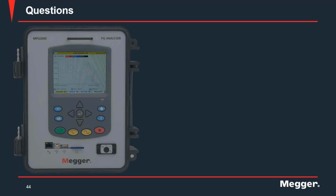One of the key things you may also end up getting into is what's called supra harmonics. These are harmonics that go up to about 150 kilohertz. And really right now, there are no standards on them. They're really in their infancy, and they're even discussing the proper methodologies of how to record them. Even with this type of thing, you can get induced signals in the line at those frequencies.